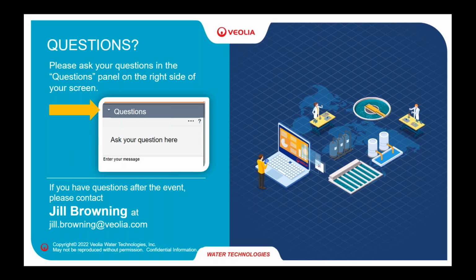So the ORPs are higher. The environment is less reducing in the MBBR for the tracer than in the classical MBBR. Also, because the kinetics are faster, the retention time will be lower. That's the other aspect. But to be honest with you, it is very similar, just a question of degrees. So a little bit less reducing condition and a little bit lower retention time.